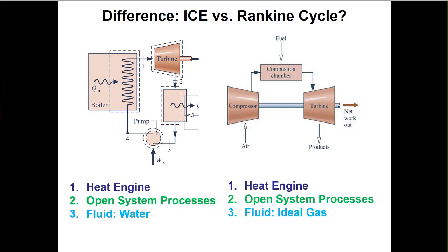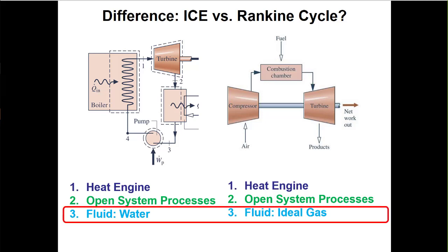So here, we're going to do the analysis. The symbolic solutions will look very similar to what we did for the Rankine cycle. But when we ask ourselves, what's the fluid? Remember, that's the question we ask when we're trying to say, how do I fix the state? When we ask that, it'll look more like an internal combustion engine. So we're going to use things like the ideal gas law. We're going to look for isentropic processes so we can use those special isentropic relationships. Maybe we'll have to use table 822 to find things like PRs and VRs and U's and H's, and S superscript zeros if we have to do some second law stuff. So this is the difference from the Rankine cycle. This is what makes it a little bit like an internal combustion engine. So 2 of our 3 questions are the same as the Rankine cycle, but one of them is different. How we fix the states is going to be different.